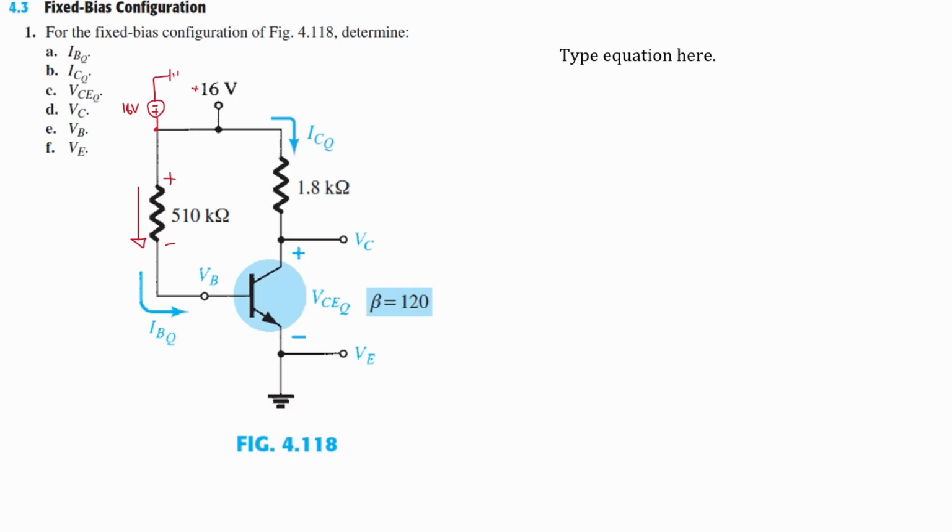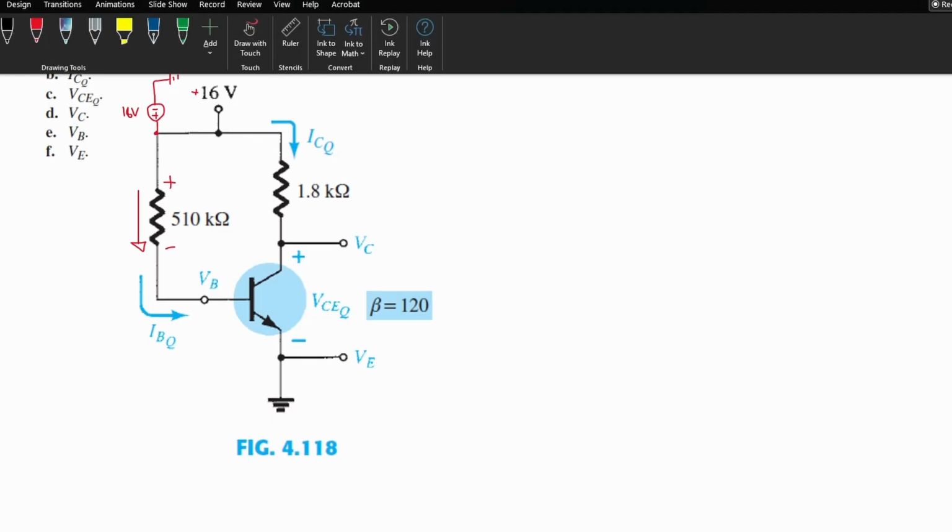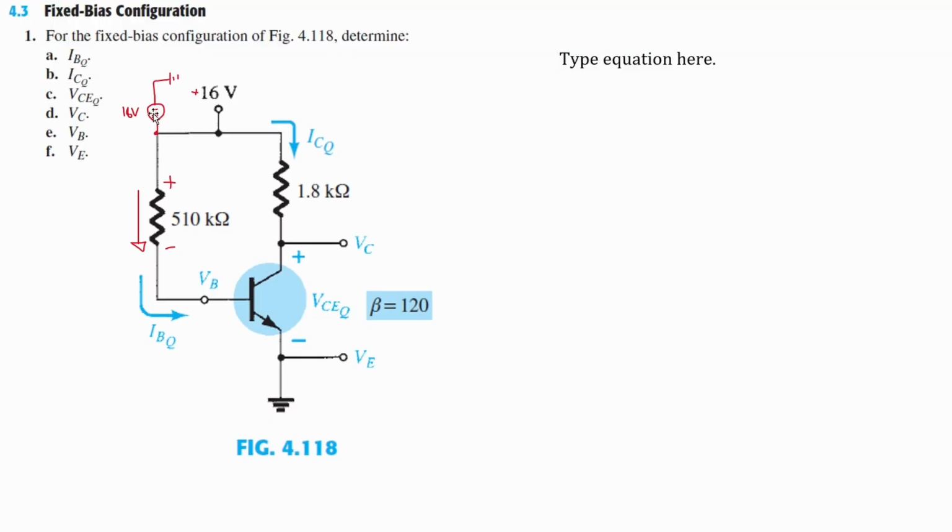So, let's do the KVL. Let me type. So, first, anong gagawin natin? So, first, KVL natin, dadaan siya dito sa 16 volts and lumabas yung current sa positive side. So, positive 16. And then, next is here. Voltage right here. And lumalabas yung current sa negative side. So, minus the current. Voltage dito is current times resistance. So, the current, IB, times 15K ohms.